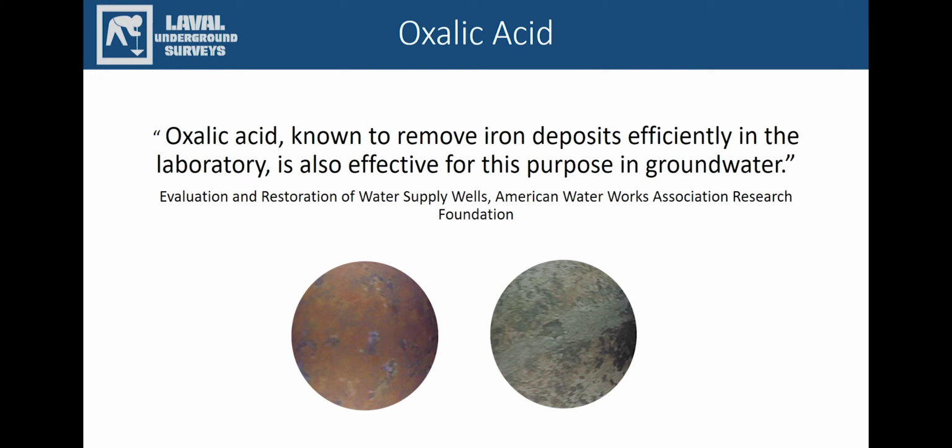The recommendation is to pair this chemical with a mineral scale removal product to treat both the iron bacteria and the mineral scaling. For biofouling treatments, it's important to know what formation the well is sat in. If a biofouled well is sat in a limestone formation, you'll want to make sure to use a scale removal product as well as a biofouling reducer to treat both issues and not end up with a sour byproduct.